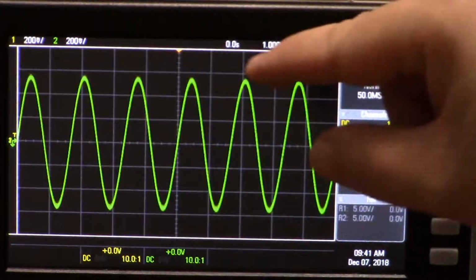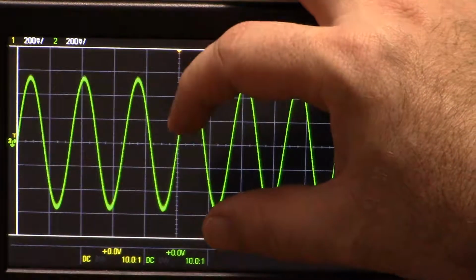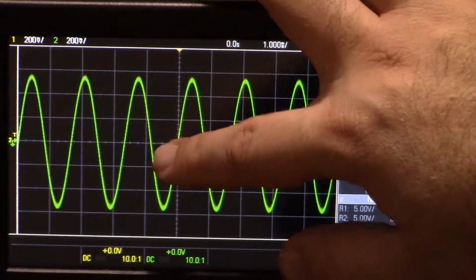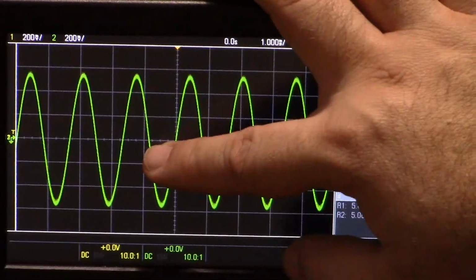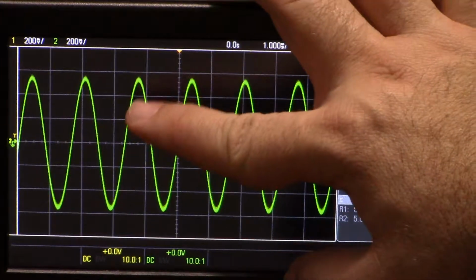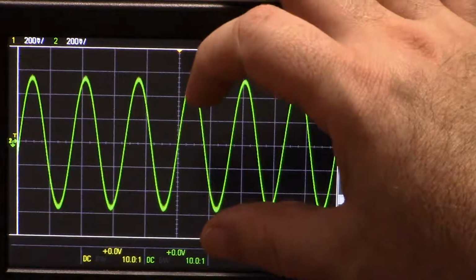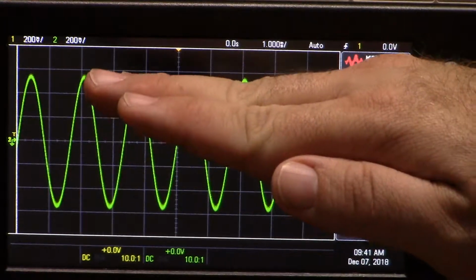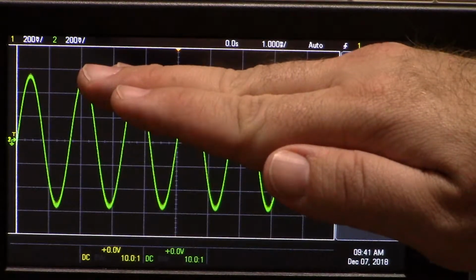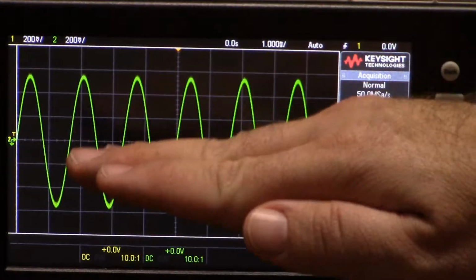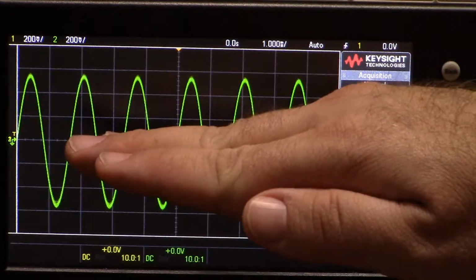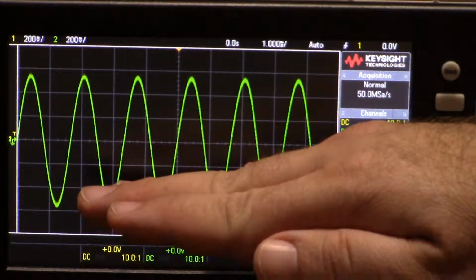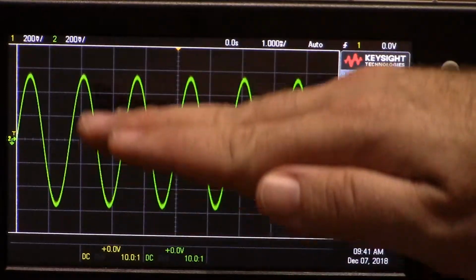Now, if you recall the amplifier, remember the emitter resistor that we usually assign about 1 volt to? For this one at maximum volume, that would actually not be enough because the value of that voltage drop varies. If we set that at 1 volt when the signal is at 0 and it's, let's say, 500 millivolts up and 500 millivolts down, that resistor would have a 1 volt drop here, a 1.5 volt drop here, and a 0.5 volt drop here because the signal is changing that.